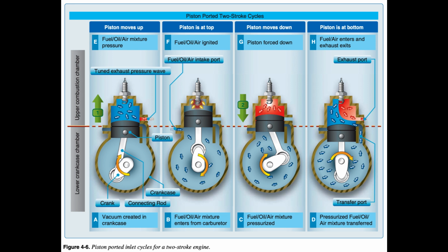The design of the exhaust converging section causes a returning pressure wave to push the fresh fuel/air charge back into the exhaust port before the cylinder closes off that port. Called pulse charging, it is another important function of the exhaust system. Figure 4-6e. Tuned exhaust systems are typically tuned to a particular RPM range. The more a certain RPM range is emphasized, the less effective the engine will operate at other RPM.